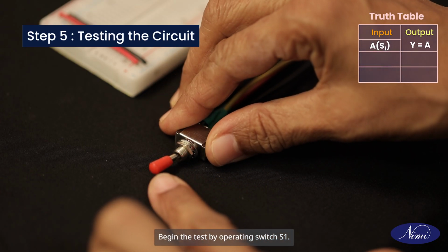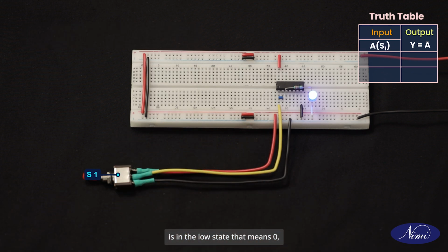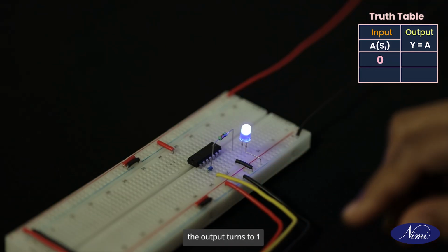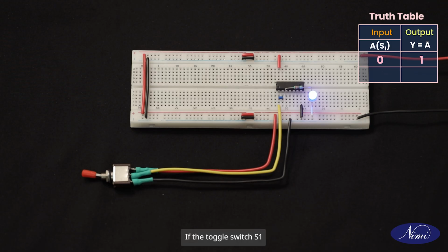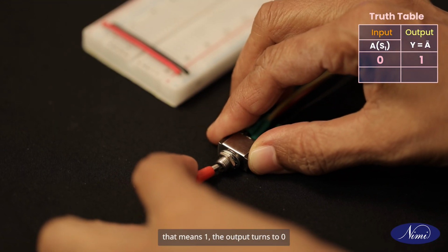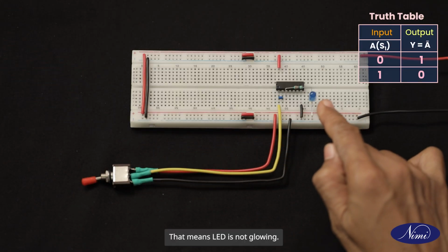Begin the test by operating switch S1. Check if the toggle switch S1 is in the low state, that means 0. The output turns to 1, that means LED is glowing. If the toggle switch S1 is in the high state, that means 1. The output turns to 0, that means LED is not glowing.